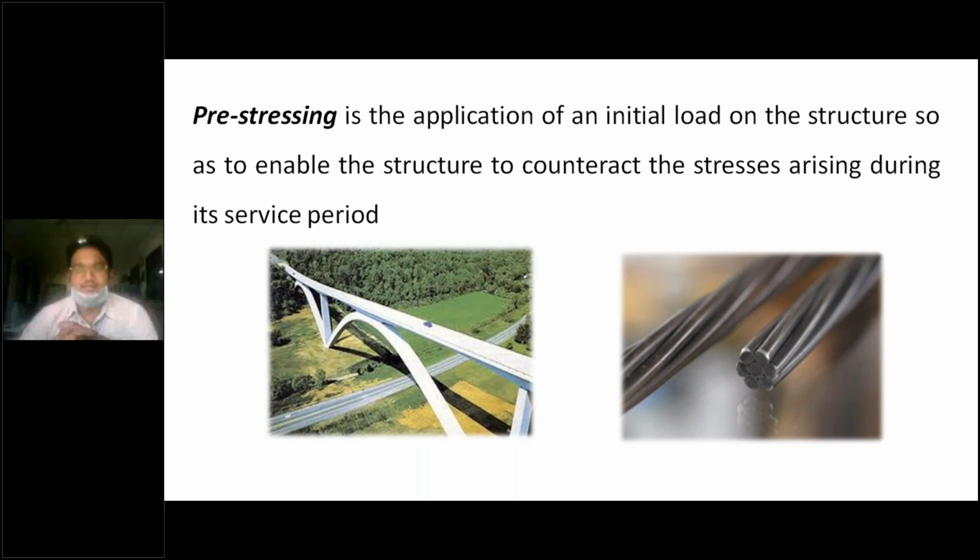Understood? That is why we apply prestressing into the concrete element or any beam or structural element, to counteract the stresses arising during the service load. Because of that service load, you may see deflection of the beam. That deflection, you are counteracting with the help of this prestressing technology. So this is the exact definition of prestressing.